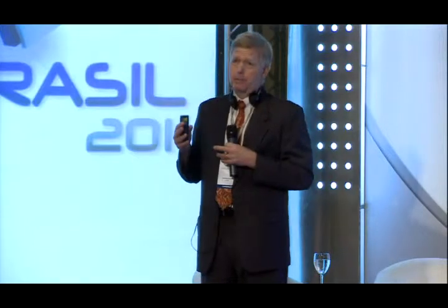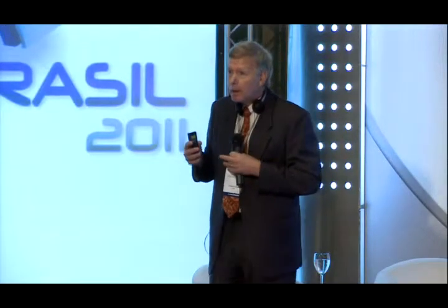Unfortunately, this is really an appearance problem where we have the white rust forming, and you might think it looks terribly corroded, but if you measure the corrosion rate over time, you find that over some years it is a much slower rate than at the beginning. Only when you see the red rust start to come do you have the steel attack, which is a functional problem. So that's good news for me to hear. After 2 years or so, this corrosion will slow down. This is good to hear.